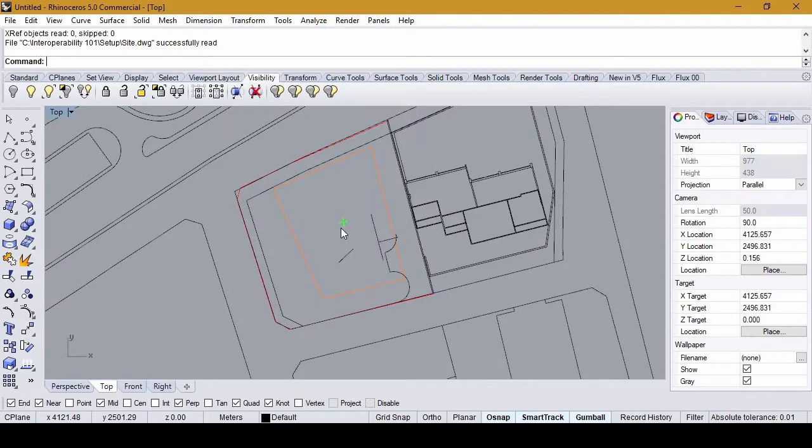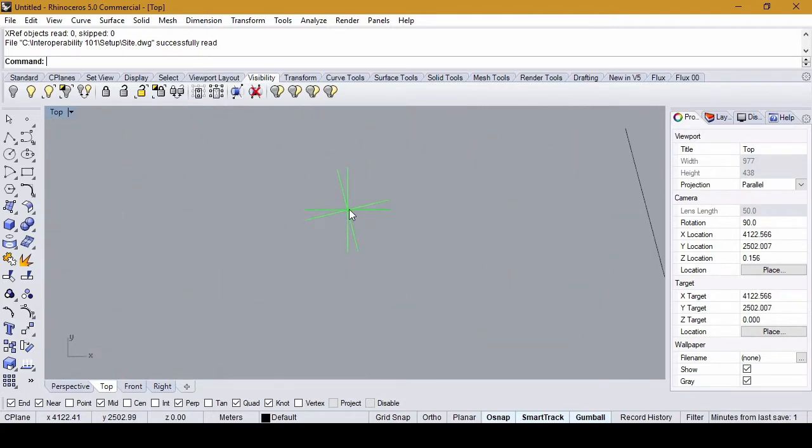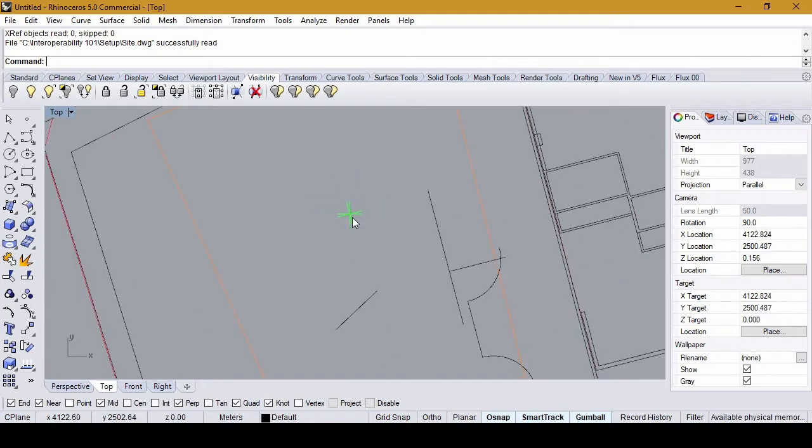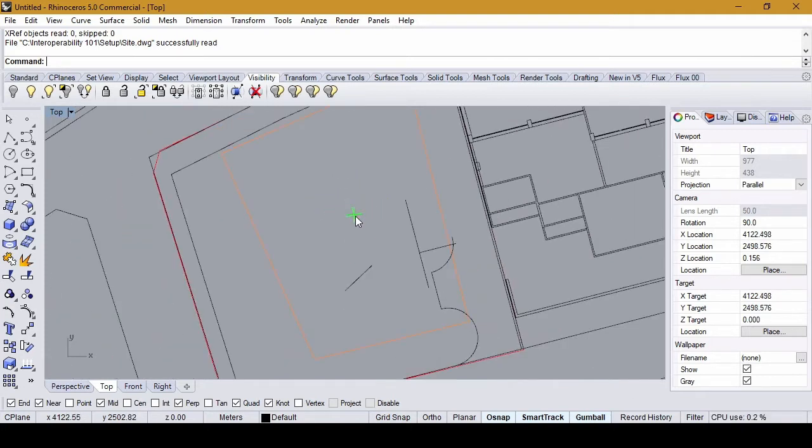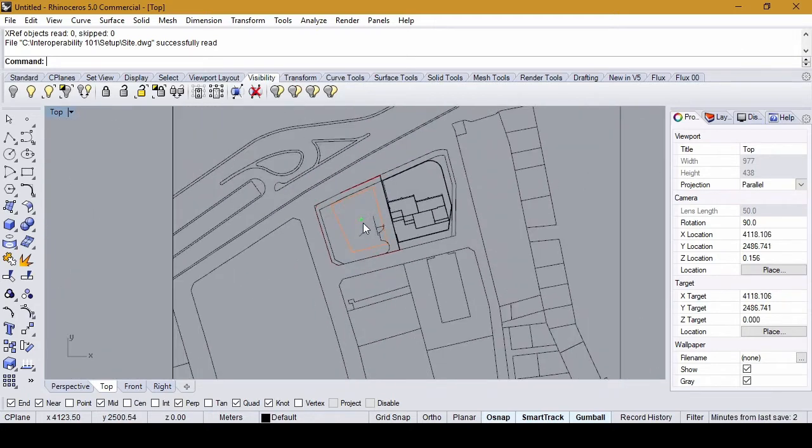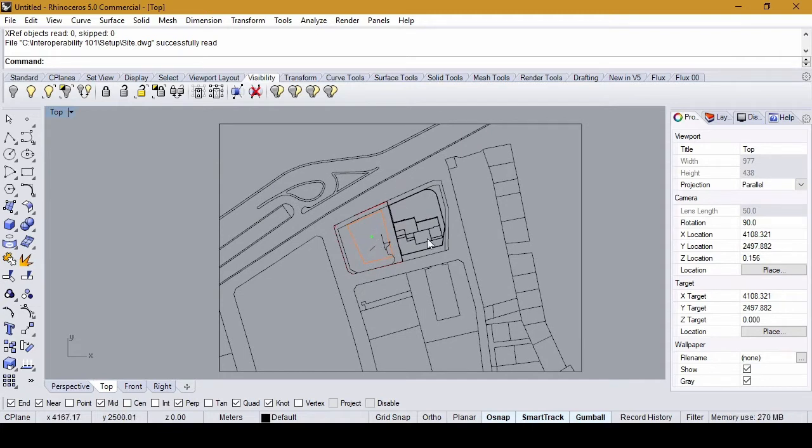We have chosen, before starting this course, a proposed origin that's going to act as our project origin, the local 000 of the project. This is maybe one of the most important things that you can do in order to have a good interaction, whether you're using Grasshopper, Dynamo, Excel, whatever, between Rhino and Revit: you want to make sure that they have the same origin, the same project origin. You also want to make sure that you are moving all this geometry closer to the origin than what normal site files or map DWG files have.